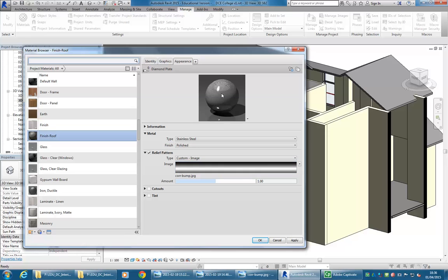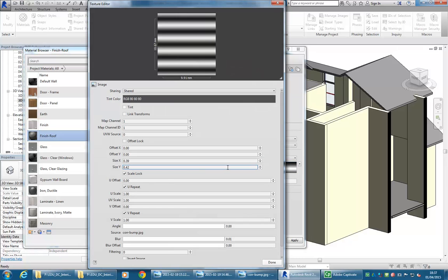Okay, so I've got this image, but notice it's hard to see the pattern there. Any idea why it's still really small? Oh yeah, it took a little while, but it's finished now. So it tells you up here it's updating if it's still changing it. But that's right, the size. So to change the size, you need to click on the swatch, not the file name. So here, when you click on the swatch, then you will see the size. Up here it tells me it is 10 mil. So that's not really a good size for an image like this.